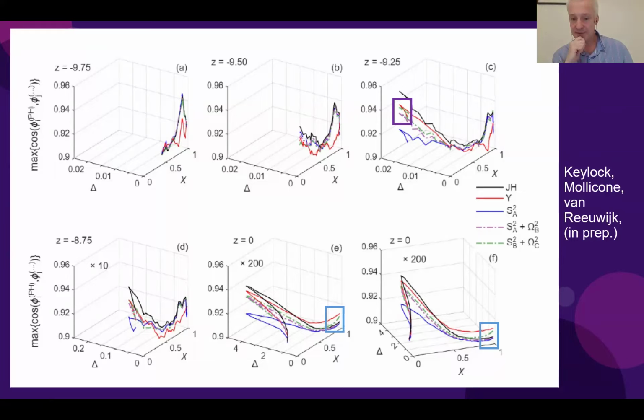But note, the other term that's asymptotically doing well in that respect is again this green line, the normal straining plus the non-normal entropy. So why the Yang and Pumir model does well is because of the effect of this, not pure entropy, pure rotation, it's this shear-induced component that is where we're perhaps seeing the action of the transient term in the strain equation that leads us to this better approximation, using fewer terms than the full approximation, which is somewhat fascinating.